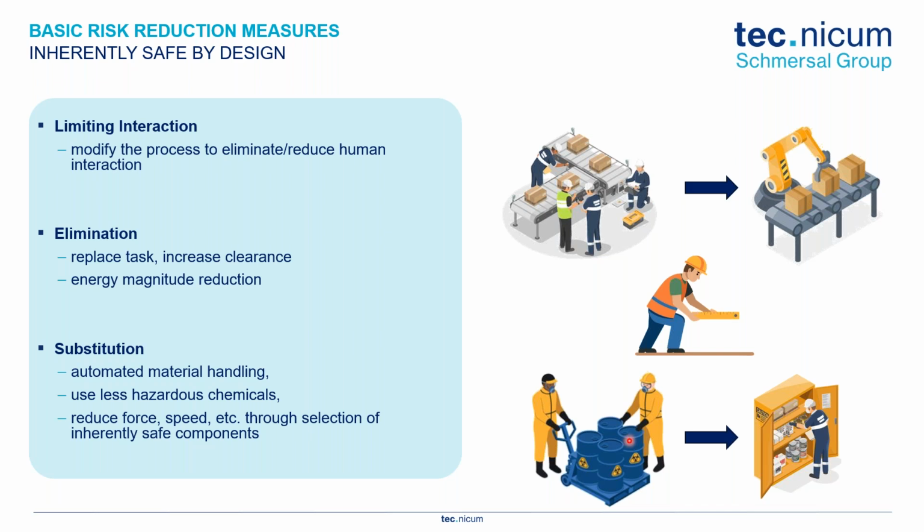Let's do some research, right? Can we perform this same task with some chemicals that are less dangerous, where maybe we don't need the additional PPE to handle this type of chemical? Let's see if we can do that. And if we do that, that is a substitution of the first identified hazard, that dangerous hazard.